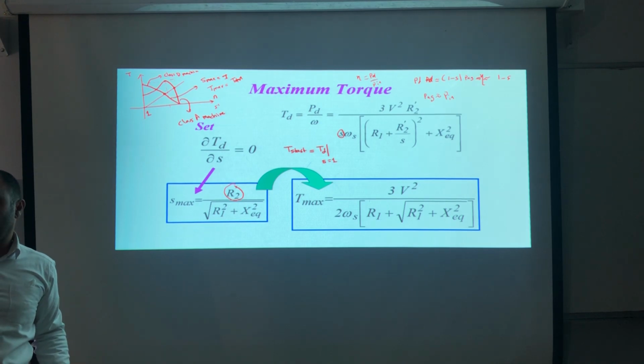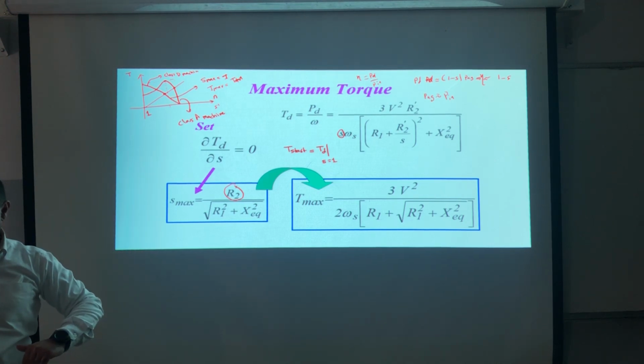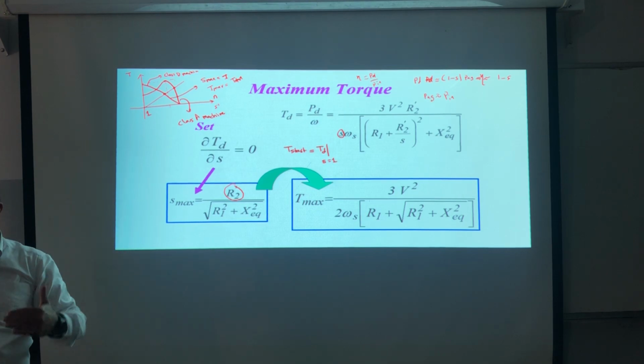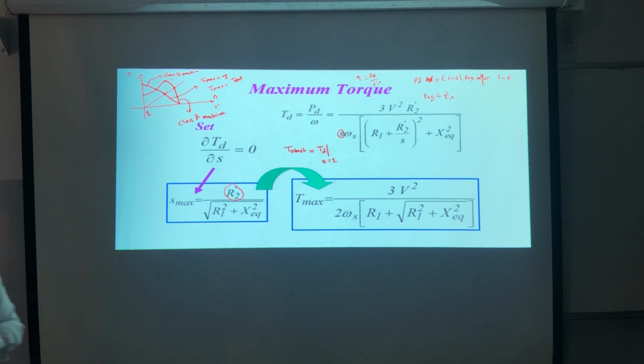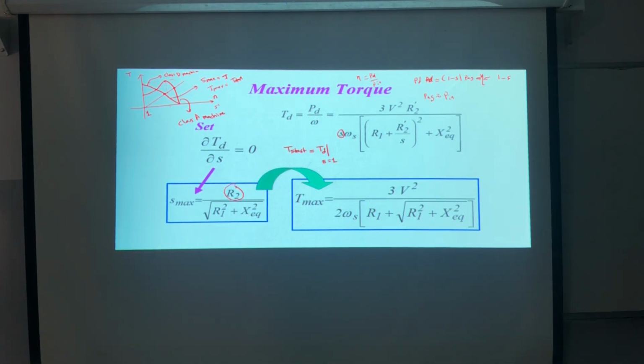The efficiency is equal to what? It will be the power in the gap, or the developed power, over Pin, correct? Now I'm living in the ideal case, Pin over Pin, and I'm having scaling, 1 minus S. So ideally, it will be 1 minus S, yeah? But S will never equal to what? To 0, yeah? We know that if I need to plot the efficiency curve as a function of S,